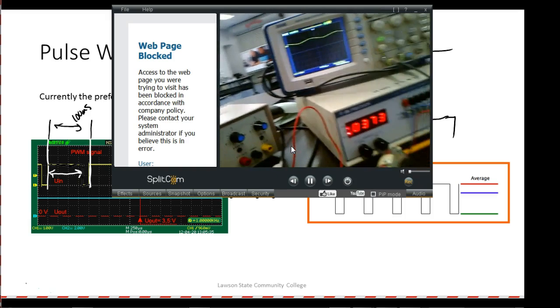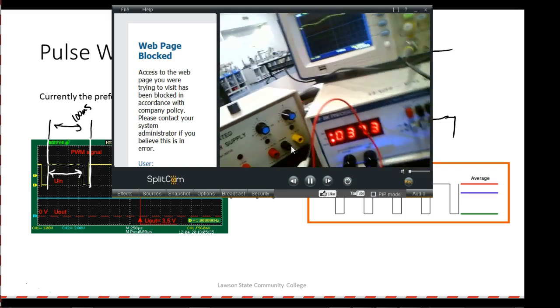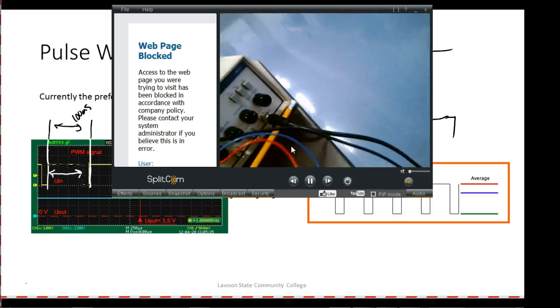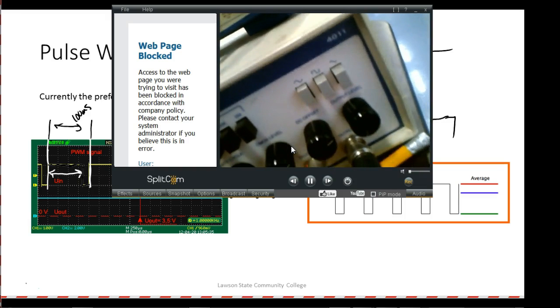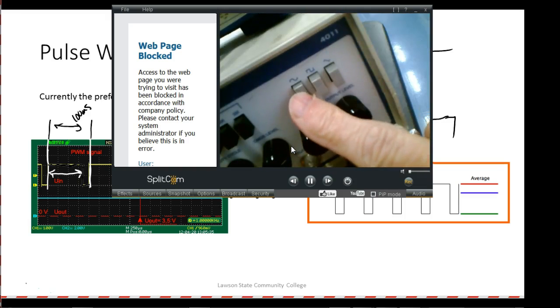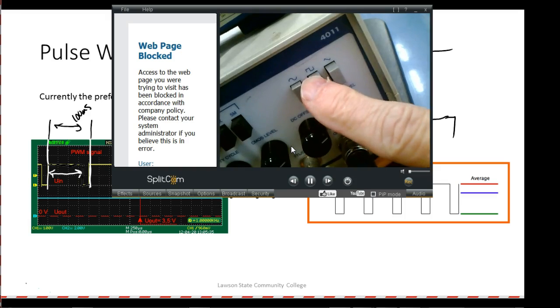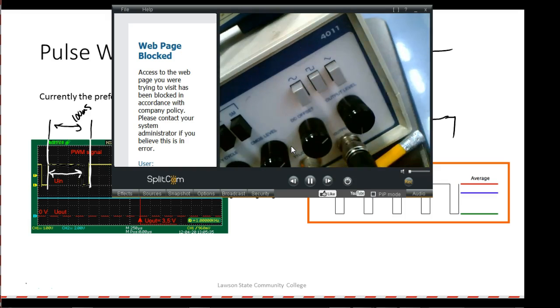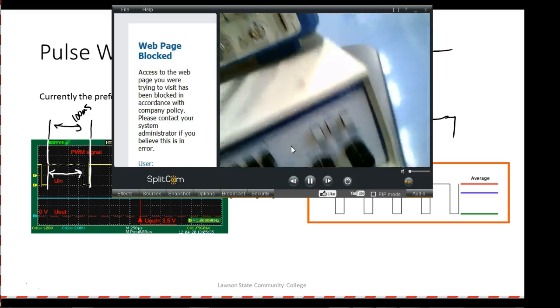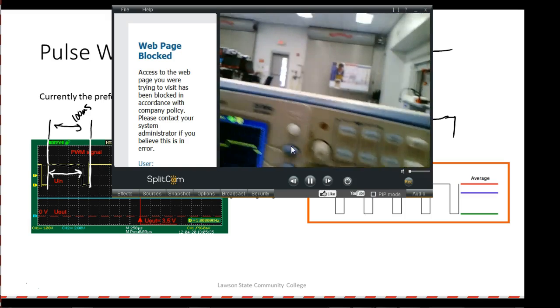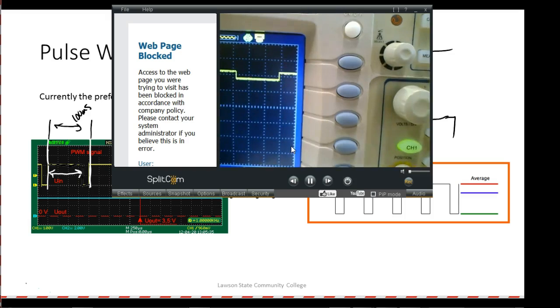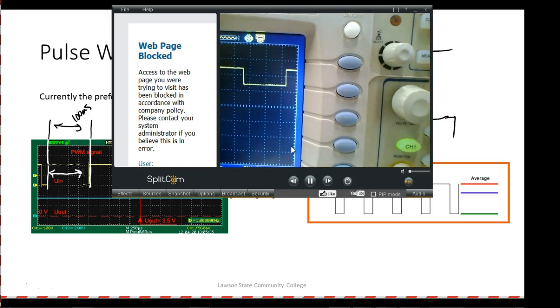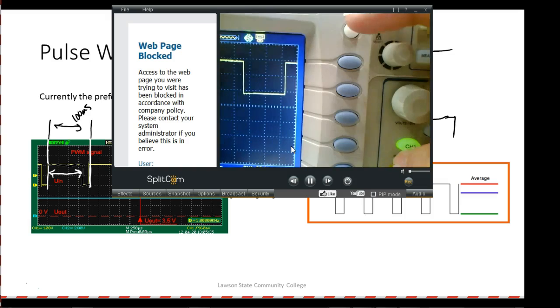So down here, the function generator is electronically created. We have 3 different signals we can tell it to generate. We can tell it to generate what we call a sine wave. This is a pulse waveform, which is what I'm going to turn it on. Okay. And then, of course, it comes up here. This is a pulse waveform. And what I'm going to do is take my volts per division and turn it up, right?